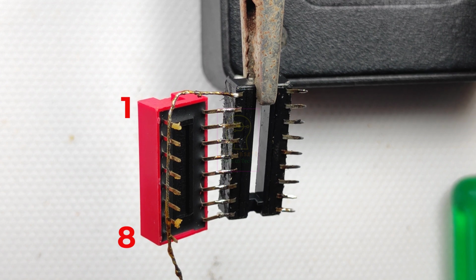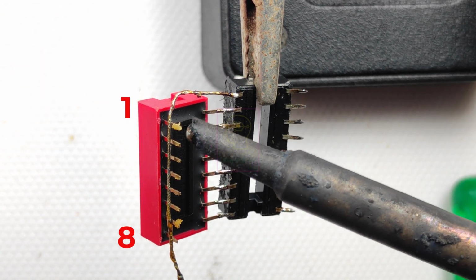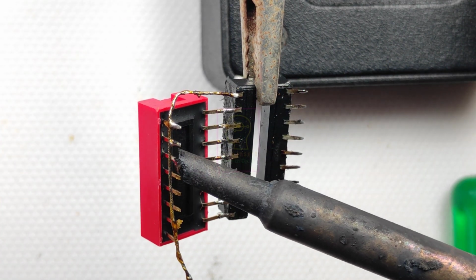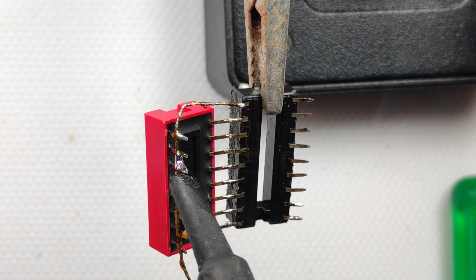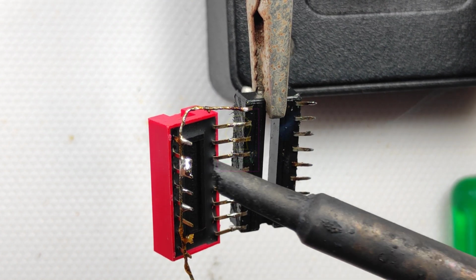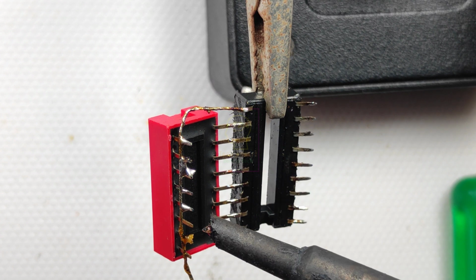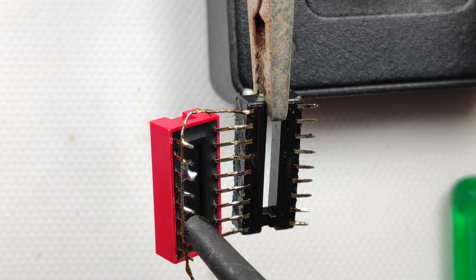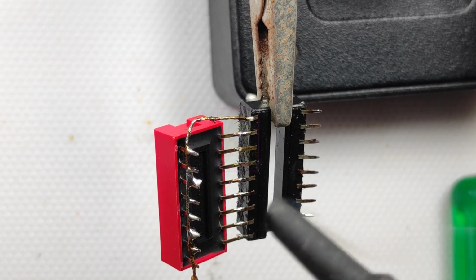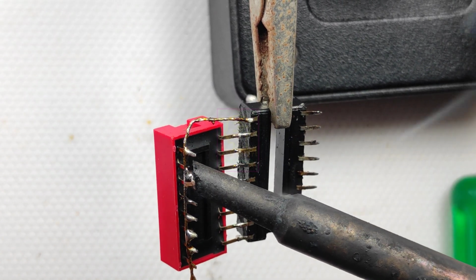You might be wondering why we use a DIP switch for fixing the address. I will tell you that. You made this circuit and it is working fine. Now your neighbor also made this. What will happen? Whenever your neighbor presses the switch in his remote, the neighbor's light will switch on. Your light will also switch on because the receiver is using the same RF frequency and the address is the same.